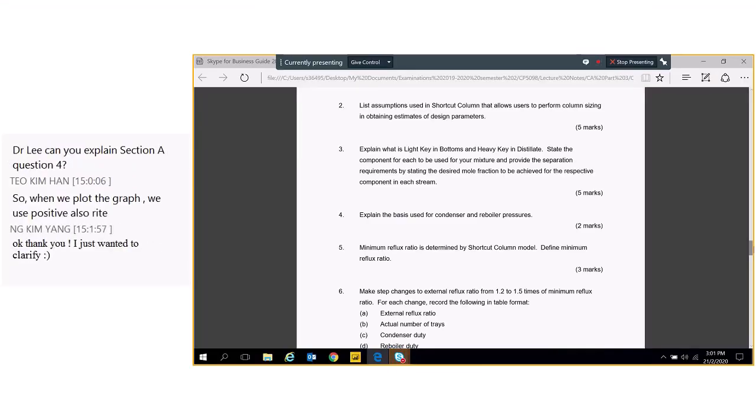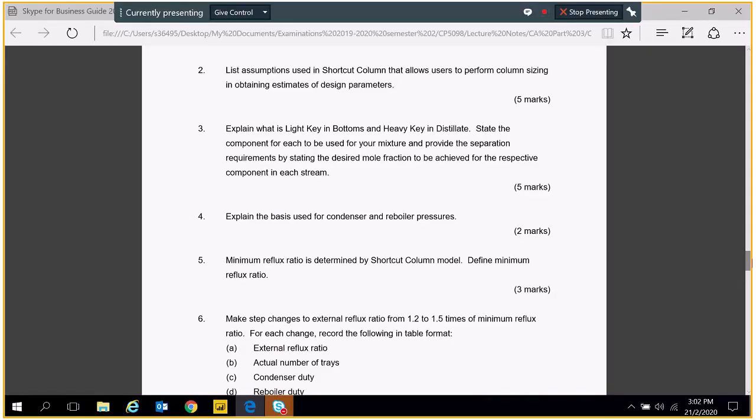Yeah, a lot more room compared to a pipe. You think of a pipe diameter as very small. The shell diameter of a shell and tube heat exchanger is much bigger. The smaller pipe diameter means the friction factor is higher, so the frictional loss is higher. Whereas for a big diameter, as in the case of a shell and tube heat exchanger, you expect the pressure loss to be smaller. Therefore, there will be a pressure drop, but it's not significant, so we just ignore that.